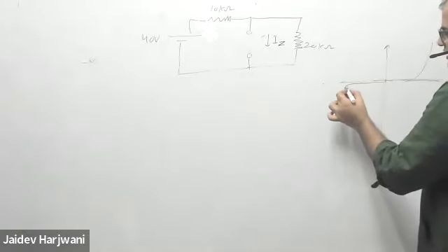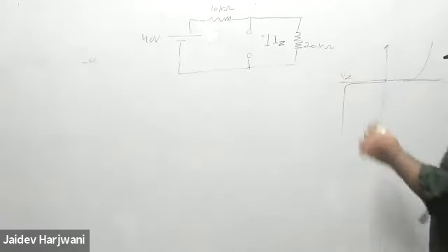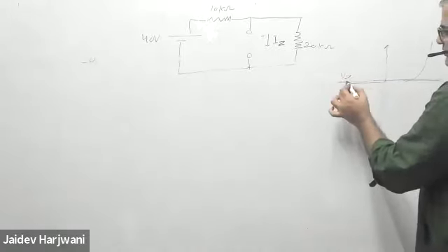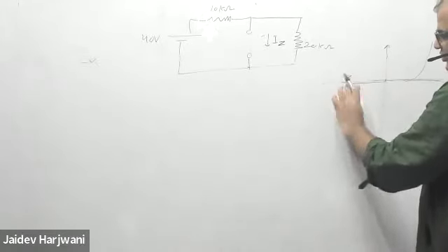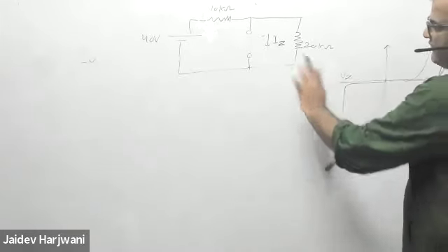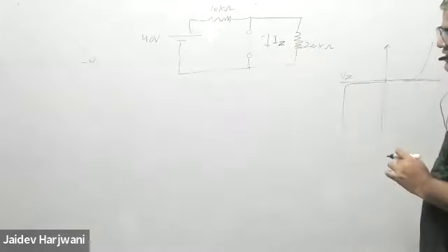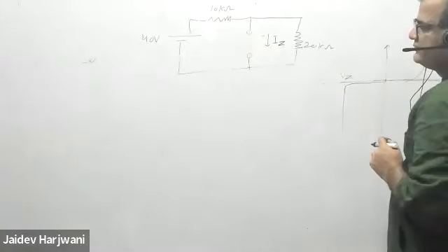Once it is in a conducting state, this is the VZ. So when the reverse bias voltage becomes more than the required VZ, the voltage across the diode will become fixed. So to check whether it is on or off, you have to see how much voltage drop is coming across this zener diode.